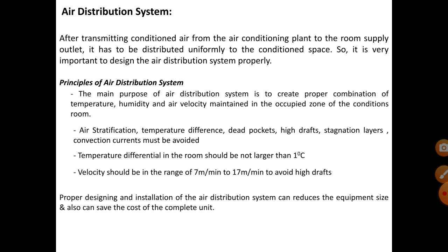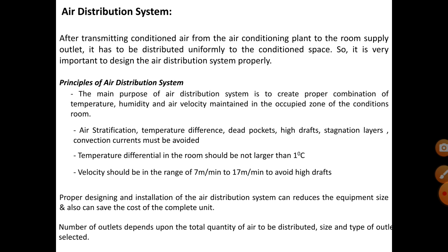See, the proper designing and installation of an air distribution system can reduce the equipment size and can also save the cost of the complete unit. And the number of outlets depends upon the total quantity of air to be distributed and the size and the type of outlet which you have selected. Now, different types of outlets we will see.